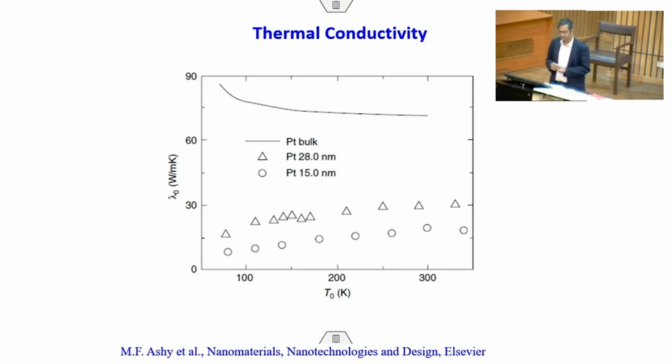So all are possible. So as you know, nanoporous materials are used as a dielectric material in the microelectronic industry because of their low dielectric constants. Okay, because the moment you use a pore, the dielectric constant will go down. However, the thermal conductivity is also low, which can cause a serious problem for these dielectric materials.